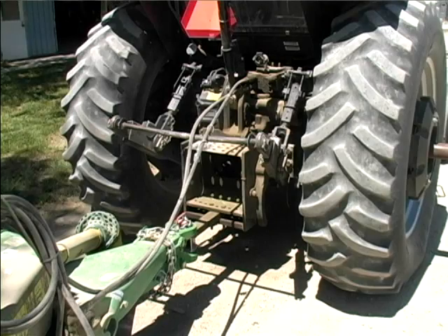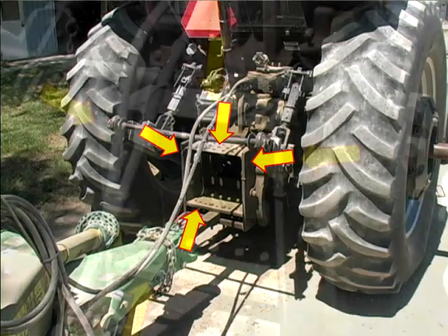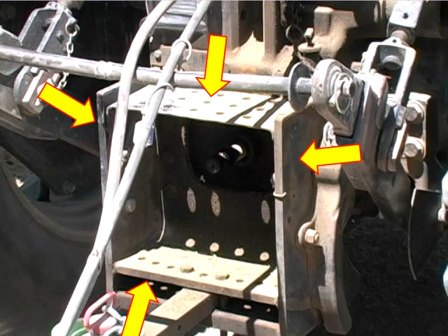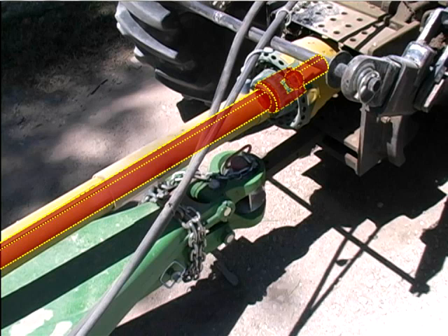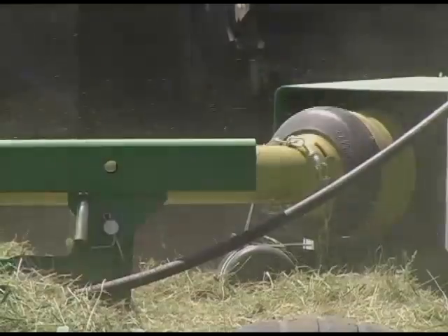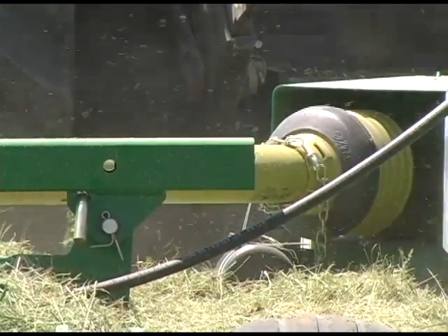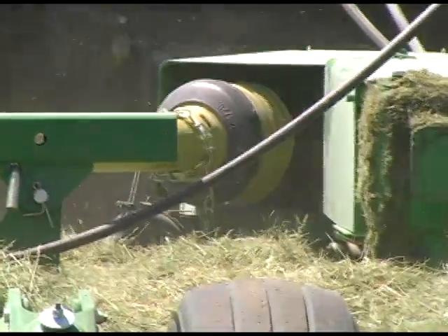As a case in point, these heavy steel guards help workers avoid stepping or leaning on the PTO stub while it is rotating. Also, the mower's driveline has an outer shield that fully encloses the moving parts. If we could see inside the shield, we would observe the actual driveline that rotates inside. Chains keep the outer shield stationary even when the driveline is spinning.